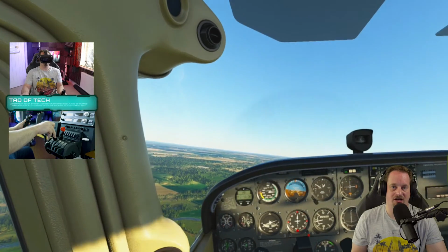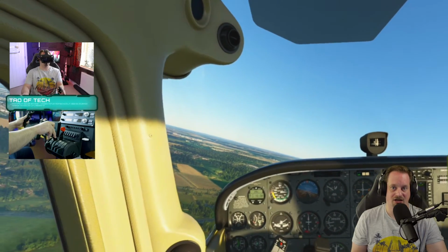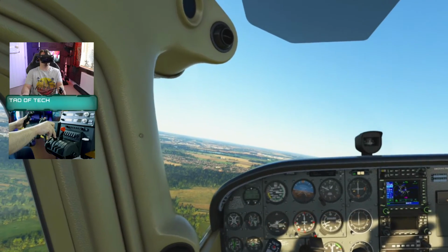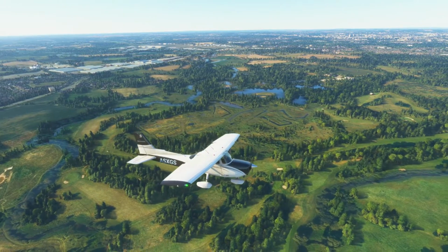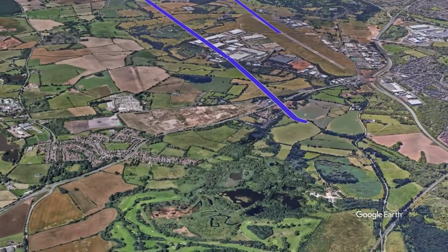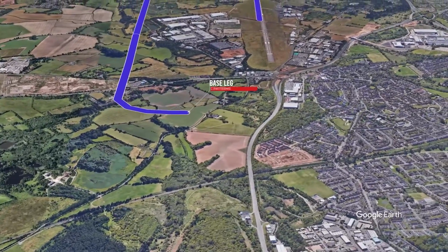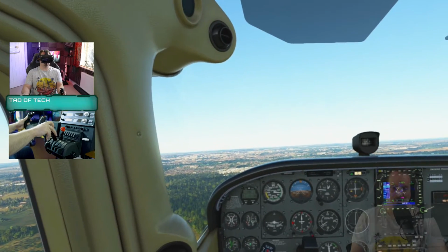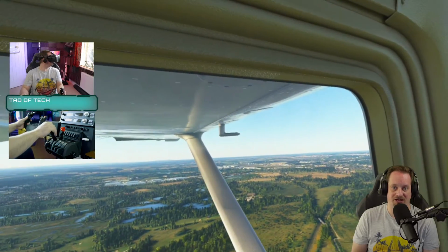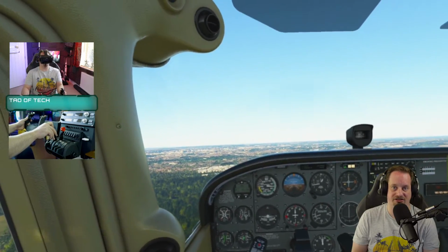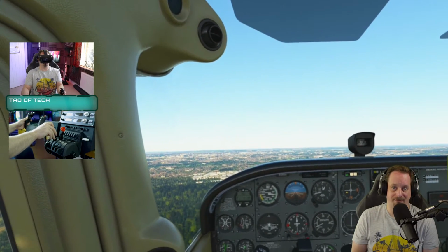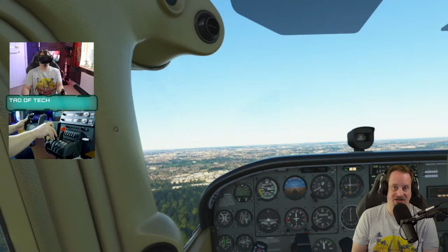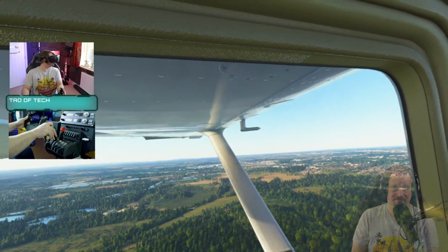So it's 45 degrees behind us, starting another standard rate turn to the left. You want to continue to descend at 200 to 300 feet per minute in this turn. We want to put one more notch of flaps in. We must make sure the wings are level before we do that. Remember, the aircraft is low and slow. If you put flaps in, which has a tendency to cause the aircraft to pitch up, when you're banking and you have unequal lift on the wings, it's the perfect recipe for a stall and spin.